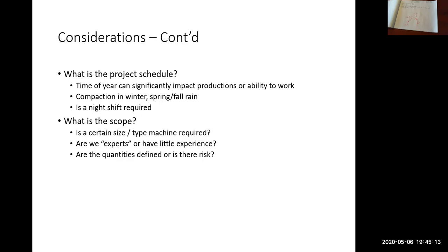The next one there, compaction in the winter. So because it rains here so much, compaction is usually not an issue. In the summer, you would have to hire a water truck to get the gravels wet. So your road gravels, for example, you would have to spray the road gravels with a water truck to bring the water content up. So there's enough moisture in the gravel in order to get the required compaction. In the winter here, it rains so much, you likely don't need a water truck. So there's a benefit to that.